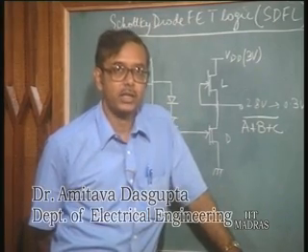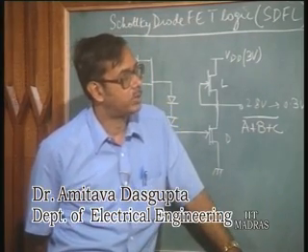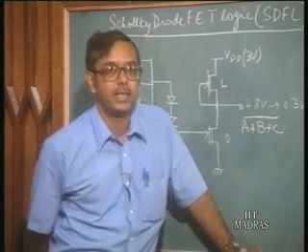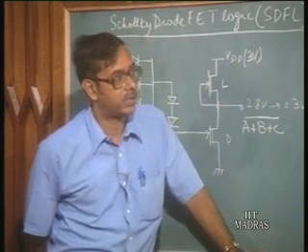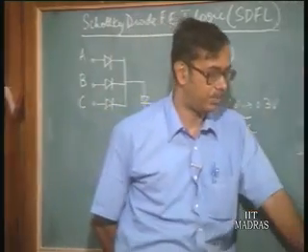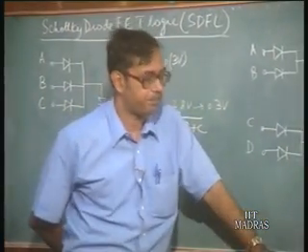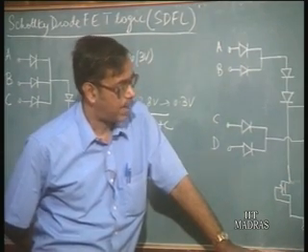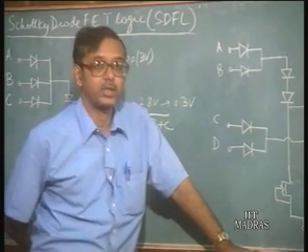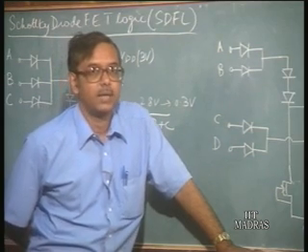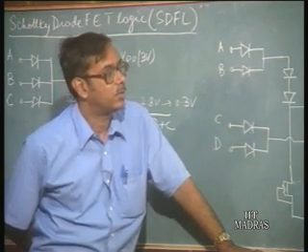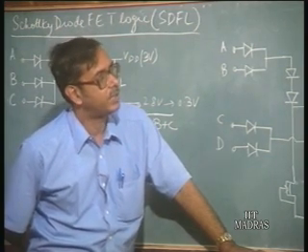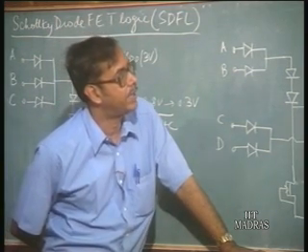So, the advantage of this circuit, to reiterate, is that it uses Schottky diodes mostly, and Schottky diodes occupy very small area, so they are suited for large scale integration. You can have a lot of complicated logic circuitry using less area, and so it is more suited for large scale integration. Also Schottky diodes, as we have already discussed, are majority carrier devices, so they are quite high speed devices as well. The disadvantage of this particular logic family is that